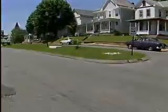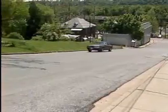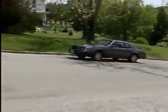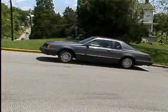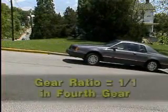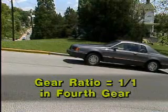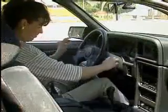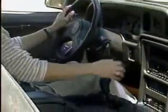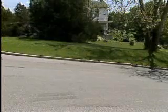Or what if you had to stop at a stop sign while on a steep hill? Well, if you try to start up in fourth gear, you may spend the rest of the day at that stop sign. That's because the gear ratio in fourth gear is about 1 to 1. Your potential for reaching a high speed will be there, but there's not enough torque to get you going. Another gear arrangement would be more suitable in this situation. In first gear, you have enough torque to get you going again.